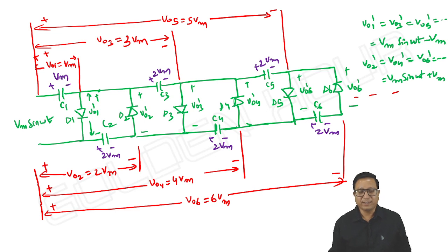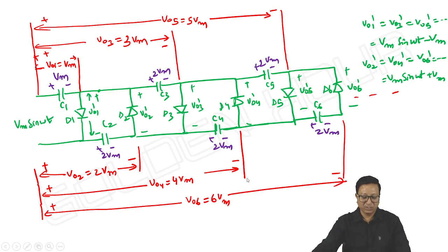Okay, they give more DC but with less current. Current is almost 0 like that. Okay, that's it. Because in steady state all the diodes are off and the capacitor voltages are constant. And this is what we take for ideal cases. Practically there is a voltage drop of 0.7 V from each stage. First to second stage 0.7 volts, second to third stage 1.4 volts, and third to fourth 2.1 volts, like that. The voltage drop will not be there under ideal conditions. Basic principle we are looking at. The basic principle of a voltage multiplier we see.